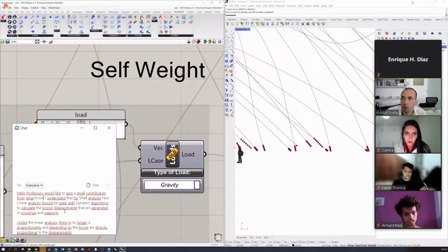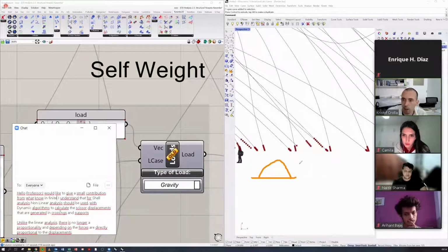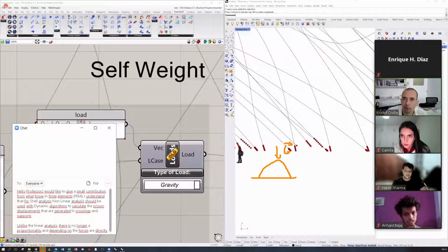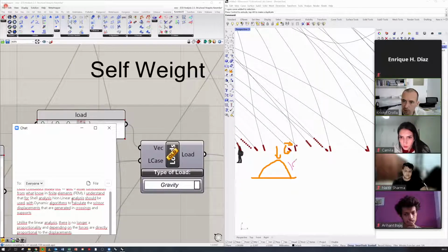In the Hong Kong building code, there's a few scenarios where you need to make sure that your pavilion works. One is, of course, just under normal self-weight, which means that the only loads that you have is basically your gravity working down on everything. In our case, that means gravity plus, on top of that, the initial strain as well. So that's load case 0. It's gravity plus initial strain.